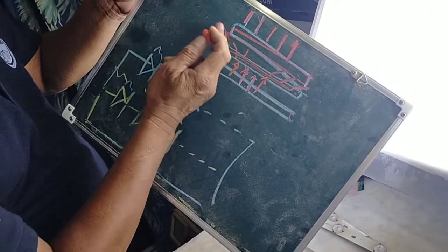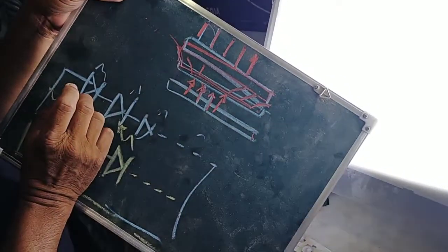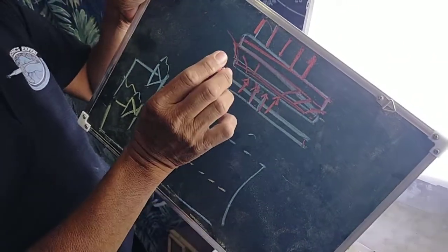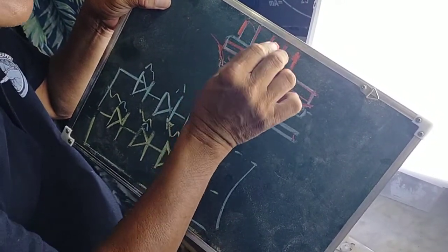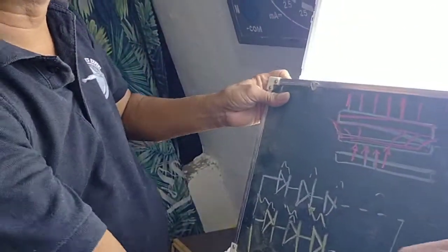The light is bent. There is a tendency to stray or to divert from its direction. So once it passes the prism sheet, which is made of polyester film, it once again aligns the light vertically towards the screen. That is the main purpose of the prism sheet, to gather again vertically the bent lights being accumulated and distributed by the diffuser sheet.